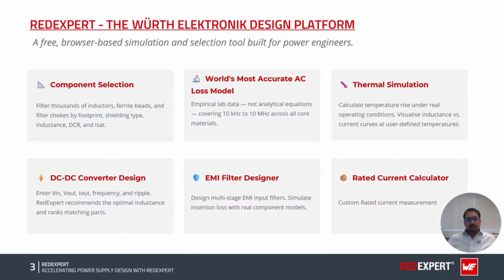Fourth, thermal simulation. You can calculate temperature rise under real operating conditions and visualize how inductance changes with current at different temperatures. And finally, you can also calculate your rated current, which I will come back to at the end of this presentation.